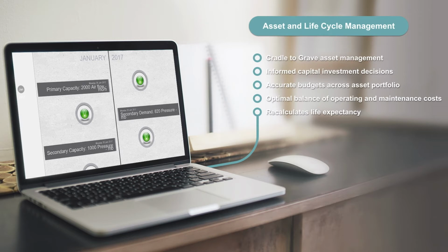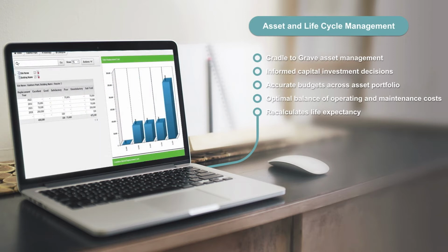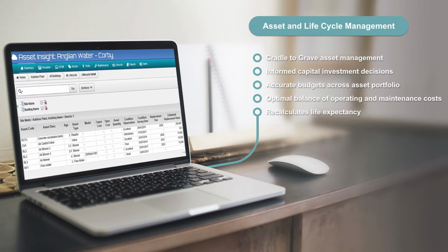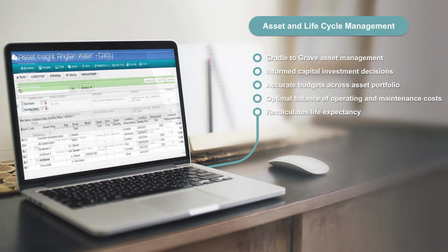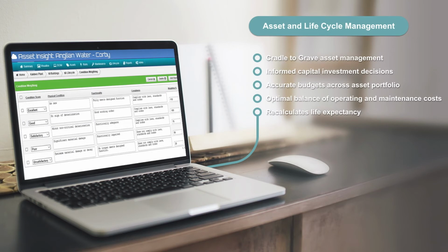This enables the AIM system to plan when assets need to be replaced and to calculate the annual spend per building, system and asset. Lifecycle planning is a key asset management concept that takes into account the whole-of-life implications of acquiring, operating, maintaining and disposing of a building asset, and is used when making strategic decisions of capital works investment and building management. The data recorded by AIM highlights when assets are likely to fail, so informed decisions can be made about replacement before a breakdown can impact business continuity.